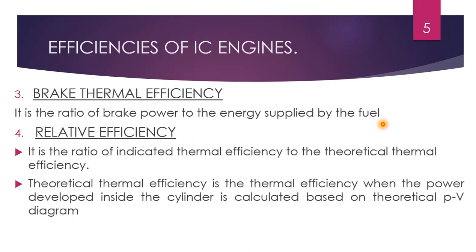And another one is relative efficiency. It is the ratio of indicated thermal efficiency to the theoretical thermal efficiency. And what is theoretical thermal efficiency? It is the thermal efficiency when the power developed inside the cylinder is calculated based on the theoretical PV diagram.